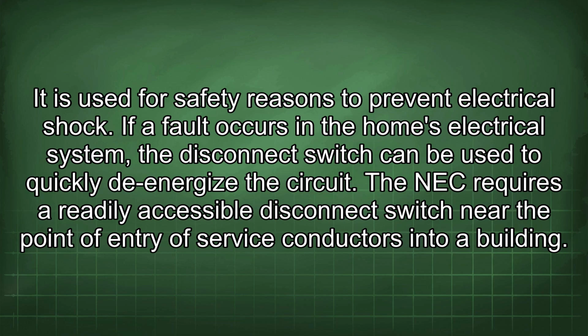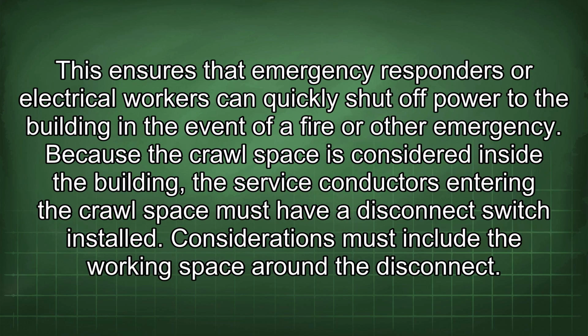The NEC requires a readily accessible disconnect switch near the point of entry of service conductors into a building. This ensures that emergency responders or electrical workers can quickly shut off power to the building in the event of a fire or other emergency. Because the crawl space is considered inside the building, the service conductors entering the crawl space must have a disconnect switch installed. Considerations must include the working space around the disconnect.